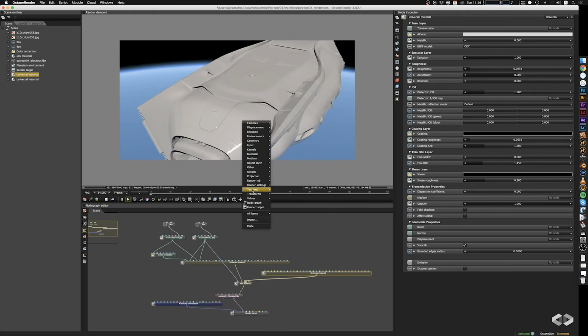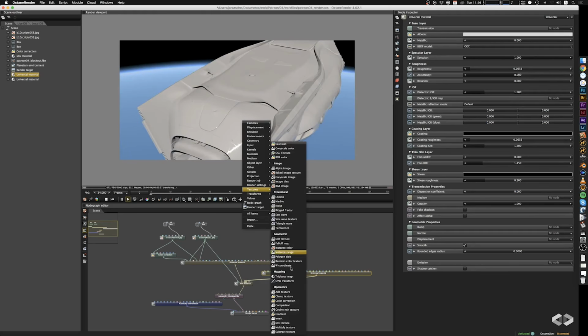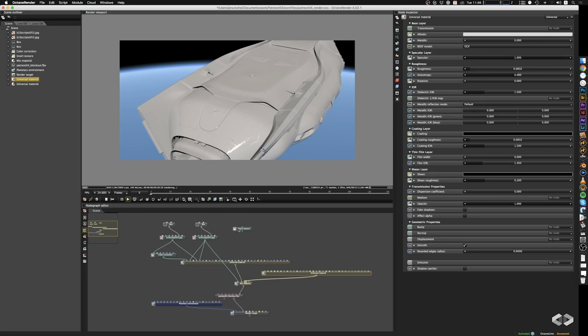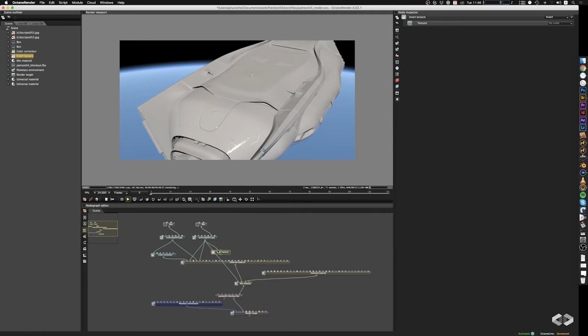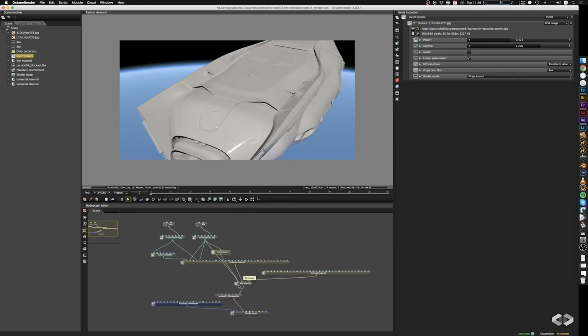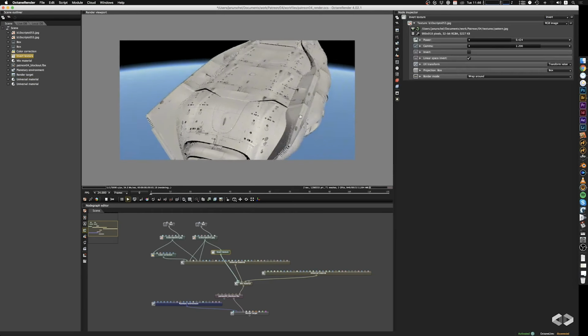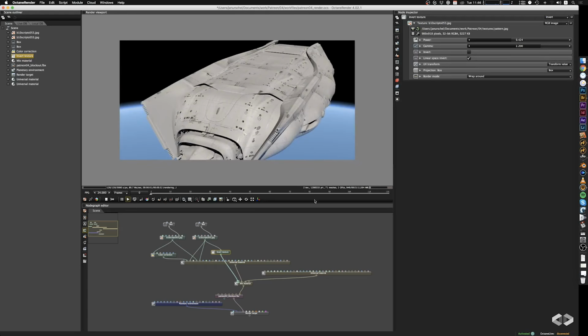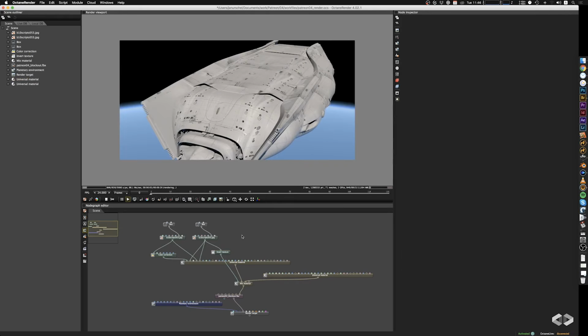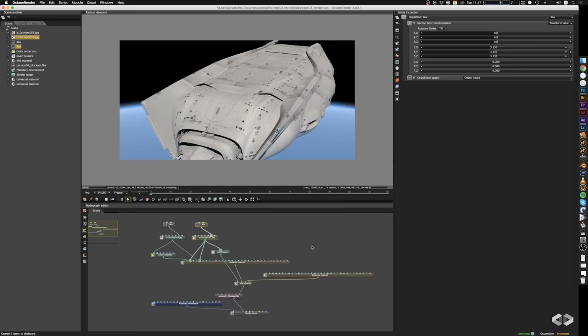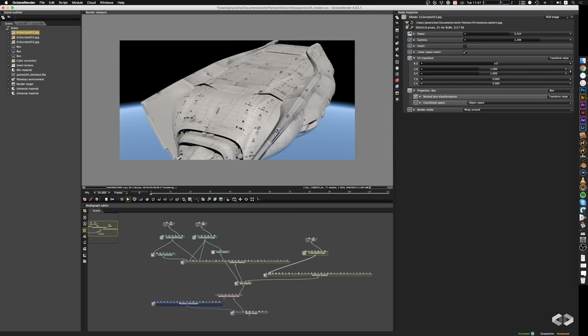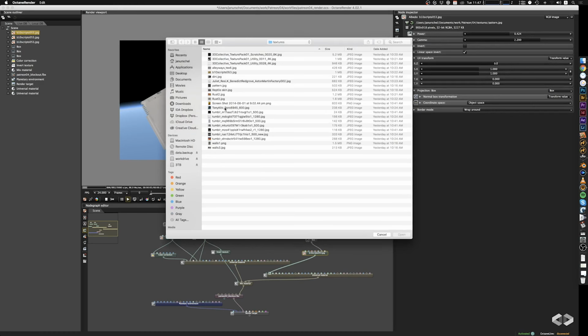So now I just created a mix material, so we can actually mix two materials together into one slot and create some kind of more complex material. And in addition, we can also tell Octane how to mix the material by plugging another image texture into the first slot of the mix material. I'll copy paste that just out of convenience and plug in a different image.